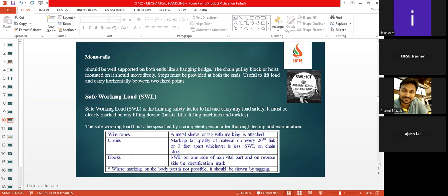For example, you'll have n number of safety belts, but we have not done any numbering for them. Generally, we went for an inspection and saw that out of 15 or out of 100, two were damaged, and we informed them to discard them. But we don't know when it was purchased or when it was last calibrated. We don't know the history of that belt itself. So if you have a history, we will have a record. For that, we need a unique identification number. It is up to the organization how they do this numbering.